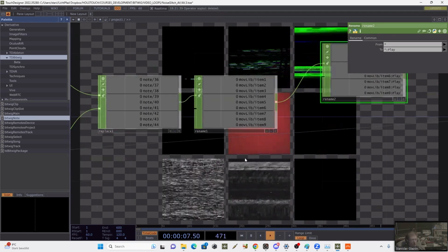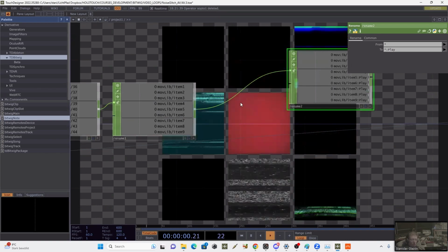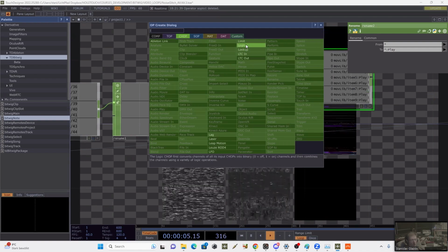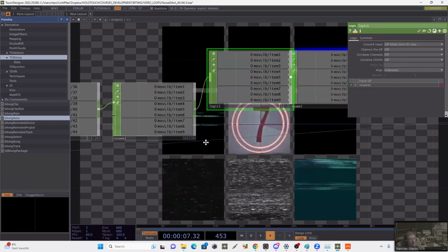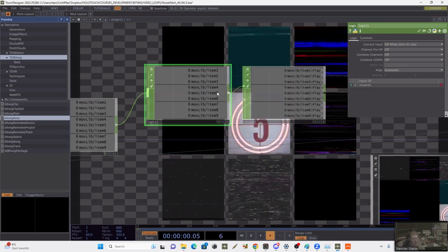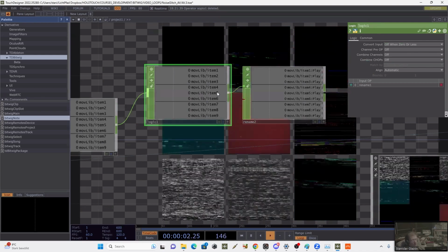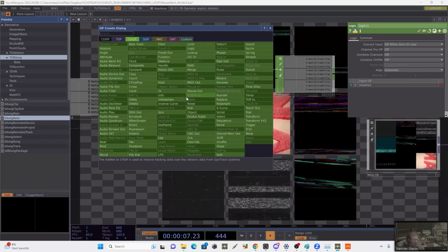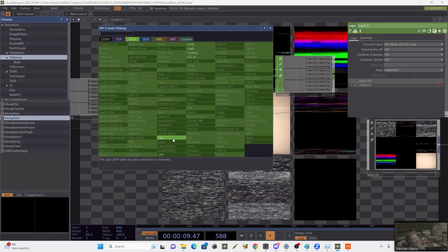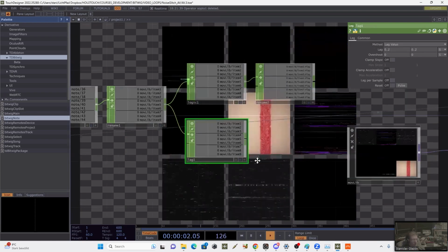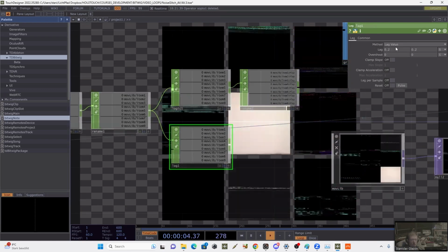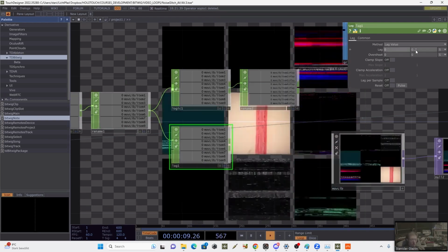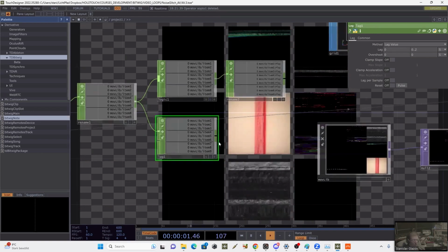So that means for the playback we just need to insert here the logic operator, because we need to set the playback from 0 to 1, and to velocity we will add some small lag to blend the transparency a bit smoother. So we just use the 0.2 on the lag out.